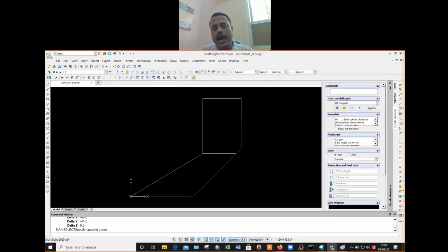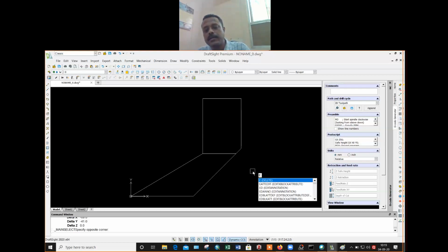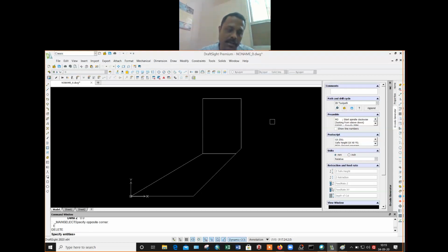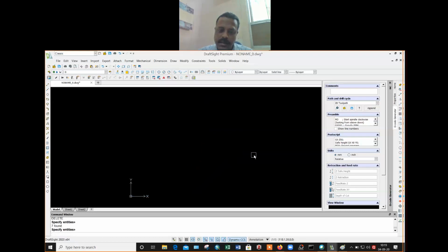Okay, I want to erase everything that I have done. This is a new command, okay? So for that I can type E or erase or delete and then select this and enter.